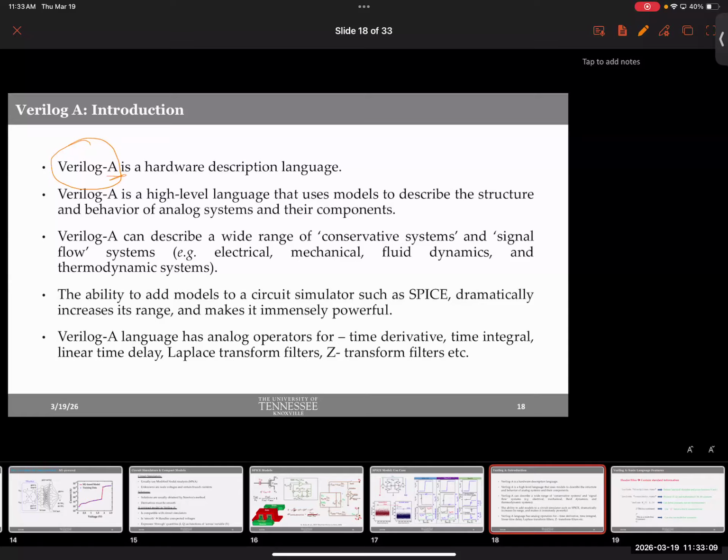It feels like it has 2 states, like low and high resistance state, but practically the resistance levels are nonlinear and they vary gradually. And there could be multiple levels of resistance as well. So for the most part, these emerging devices and materials are analog in their characteristics. So Verilog-A is very useful in modeling them.